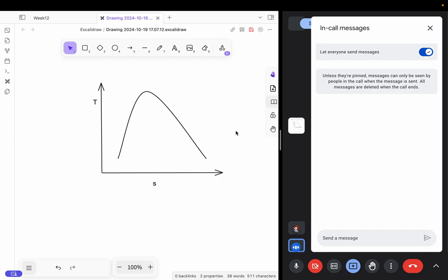So this is the vapor dome. So what are the different states? The turbine outlet will be in the superheated state. So from the superheated state, you'll come somewhere here. And from here inside the condenser, you just go till the saturated liquid state.